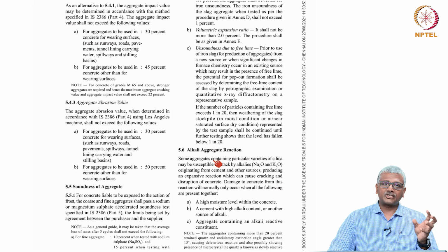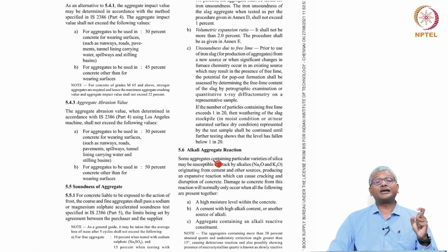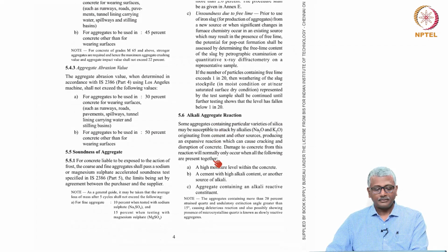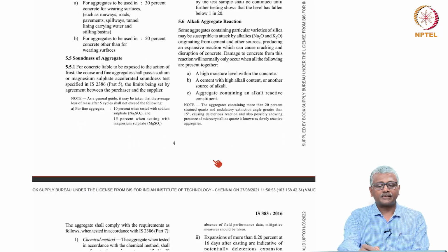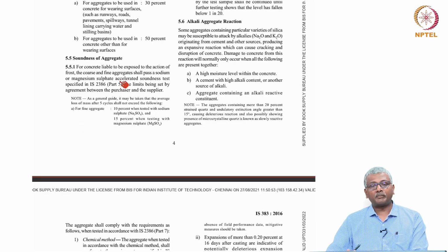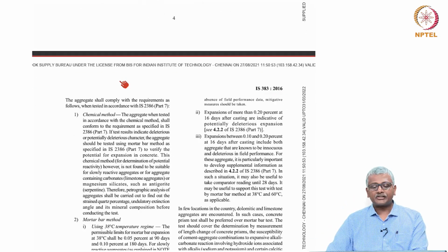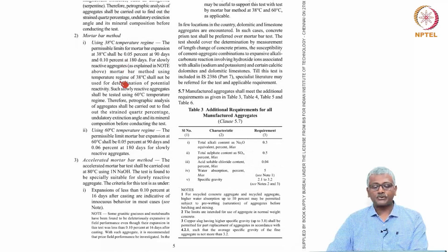But sometimes this crushing process can do some damage to the aggregate, which may make it more alkali reactive. So, you have to be careful about ascertaining that property also of the aggregates that you obtain from recycling. All of those characteristics, including soundness, need to be properly assessed, and as long as the aggregate is satisfying all of these aspects, it is capable of being used in concrete.